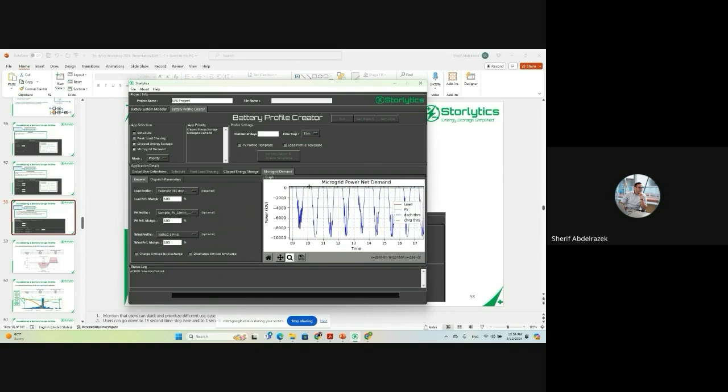Let's take these two days. A lot of days you don't get this much solar, so let's get one where we didn't get a lot of solar production. Man, sunny period. All right, here, for example. We set it to charge at 8 megawatts, so when solar production is greater than 8 megawatts, it's going to charge this delta here. For a day like this, there's just not a lot of power greater than 8 megawatts, so it's not going to have as much energy as it did here.